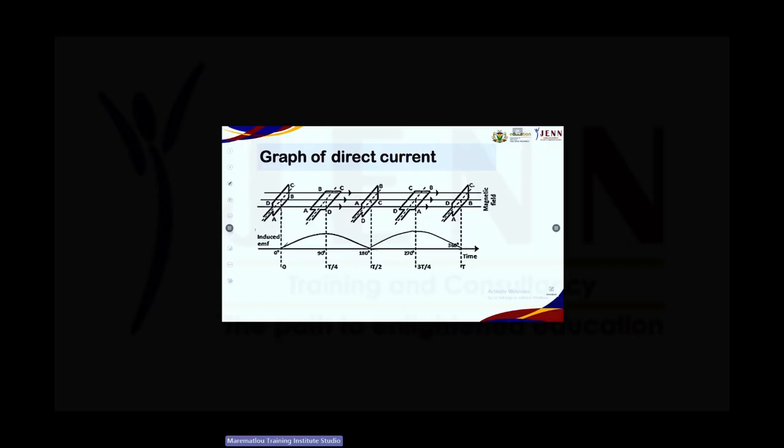When your coil is parallel with your magnetic field, then it reaches the maximum. Then it rotates again, another 90 degrees, which gives you then a total of 180. And then it rotates again to 270, meaning it cuts with a magnetic field, so creating a maximum EMF or inducing maximum EMF. And then again, if you look at this part, your magnetic field lines are going through the opening of the coil, which means then that there's going to be no EMF induced.